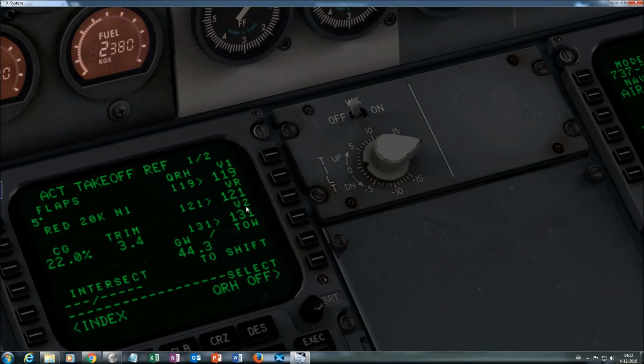Therefore, our climbing out speed has to be higher than V2, because if we are flying at exactly V2 and one of the engines fails, then at first the speed will drop back. But if the speed drops back too much, the wing doesn't generate enough lift and will stop flying, causing the plane to just fall from the sky, and we don't want that.